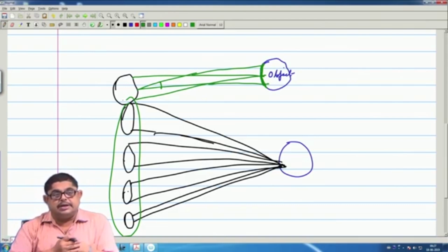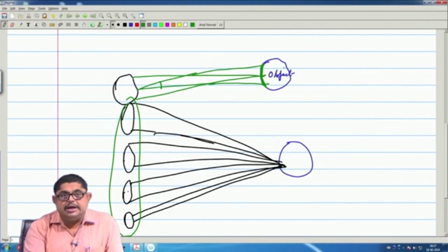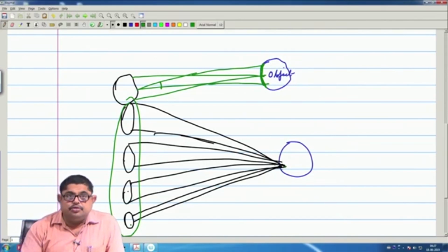that is synthesized. So, for synthesizing actually you see that if an antenna is here and it is illuminating, or if the antenna is here it is illuminating, the space phase of the return echo signals are different.